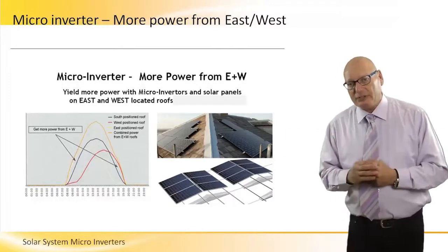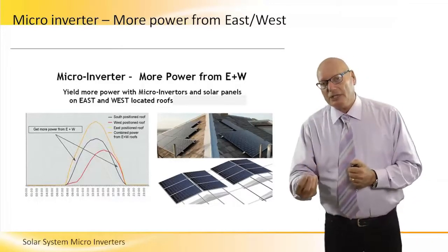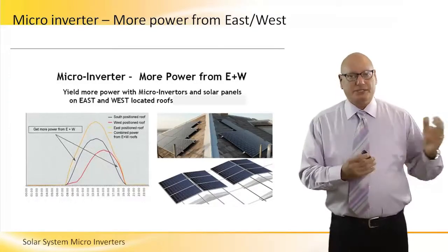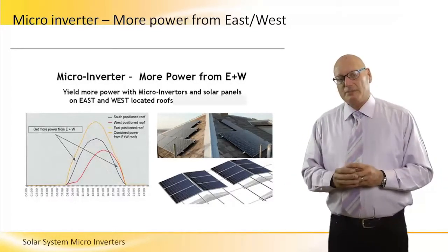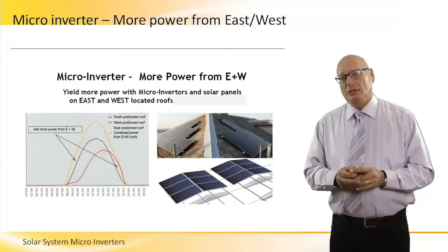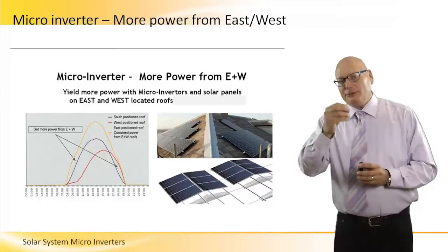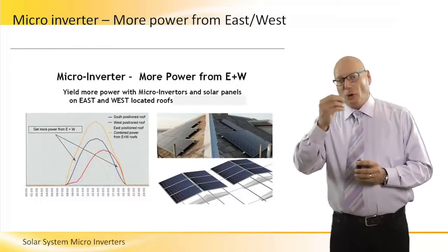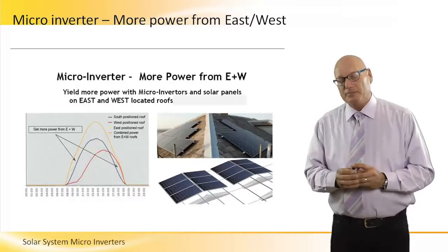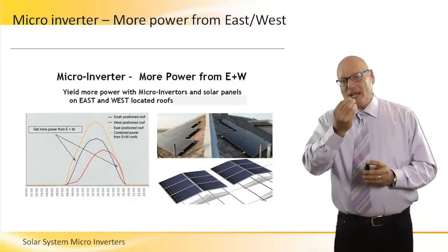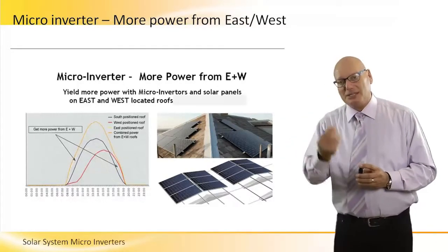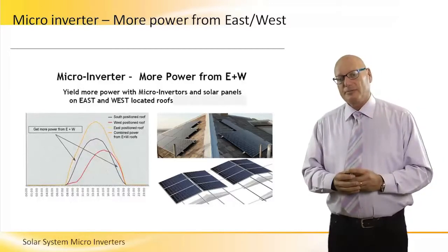And the reason we can do that is because even with lower energy coming into the panel, when the sun rises and when the sun sets, or any time there is a small angle of radiation, the IV multiplication and optimization done by the MPPT circuitry within the microinverter keeps it at the maximum. So even in morning hours and in evening hours, I can still receive a large amount of energy.